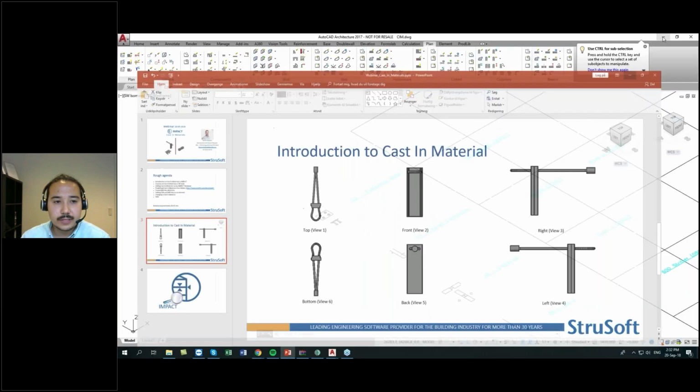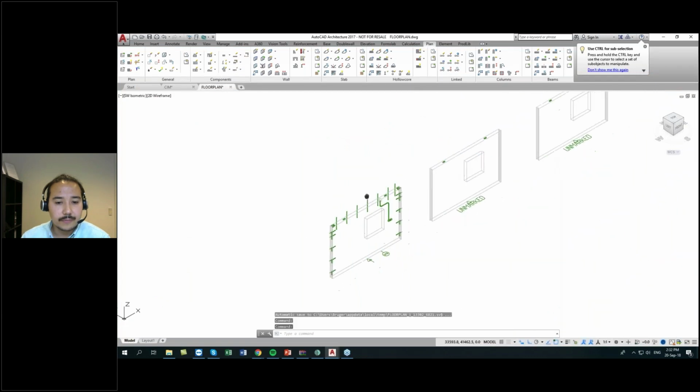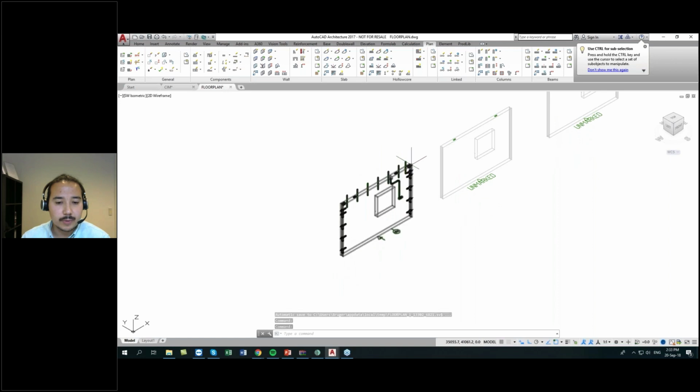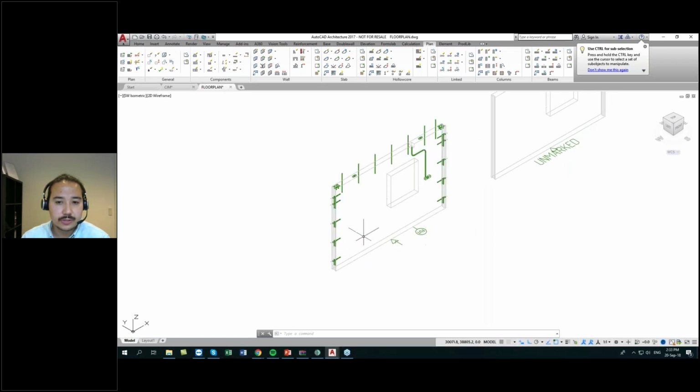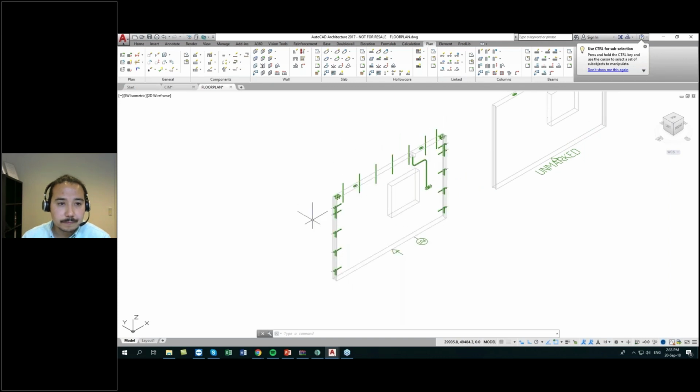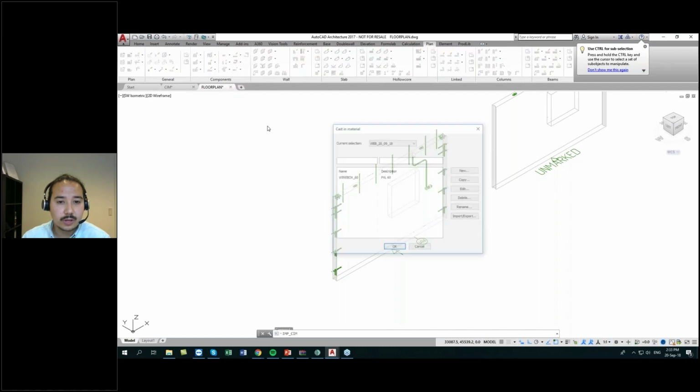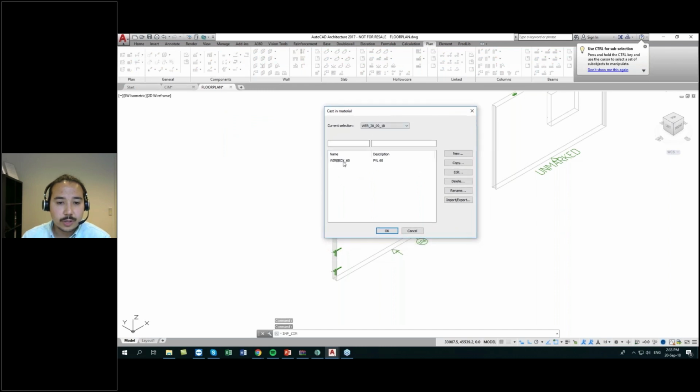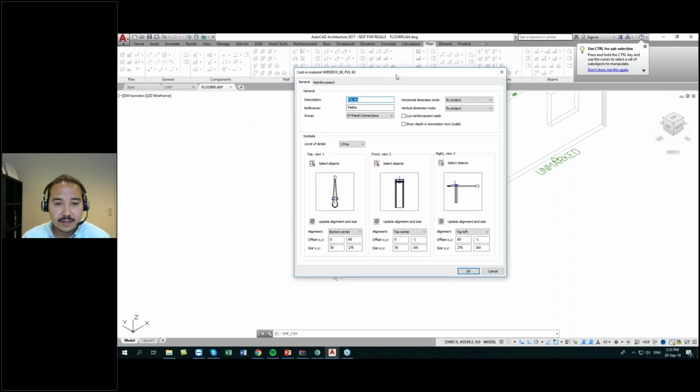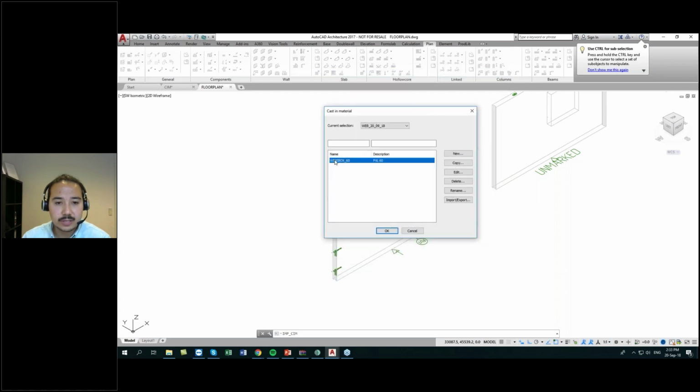So the first thing I'm going to show is the element we're going to aim for with the custom materials, how we're going to make it look when we're finished. Under the Impact module plan, on the components, we have the custom materials and this typical definition. If we open up this wirebox, we can see that the name of the custom material is wirebox_60. This name needs to be unique because this is the name put into the database, so Impact knows which custom material it is.